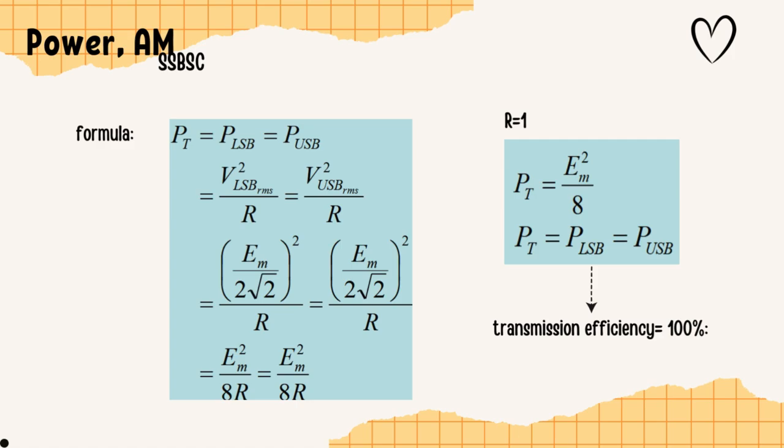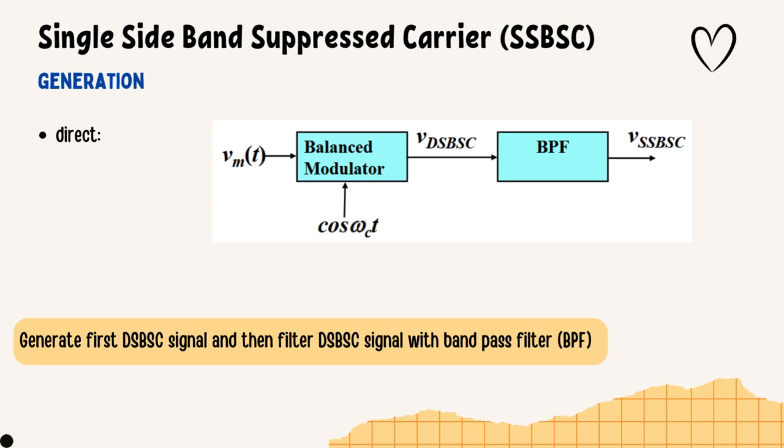So we would say that the modulation index for SSB-SC is similar to the DSB-SC, however, the carrier amplitude is suppressed and not transmitted. And for the power of SSB-SC, the power is concentrated entirely in a single transmitted sideband. Since only one sideband is transmitted and the carrier is suppressed, SSB-SC achieves the highest efficiency among the AM techniques.